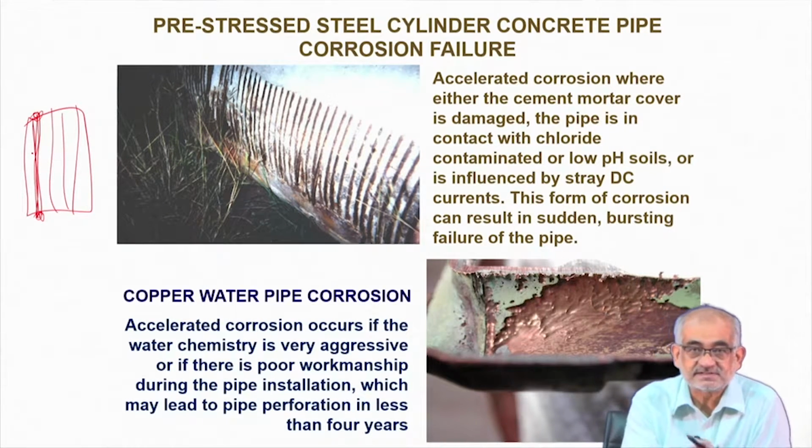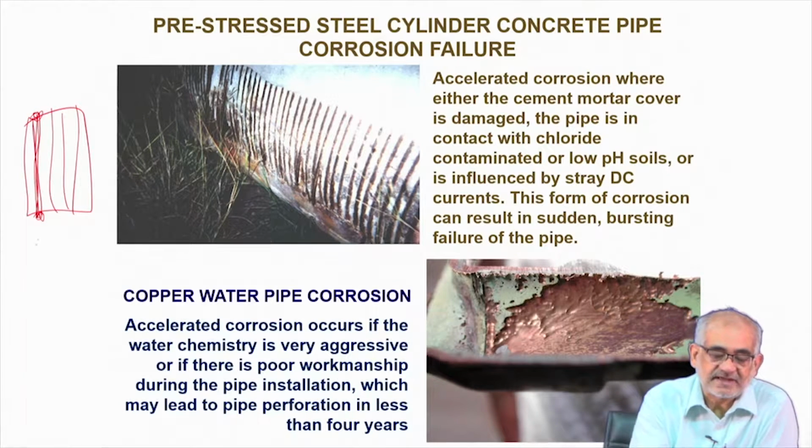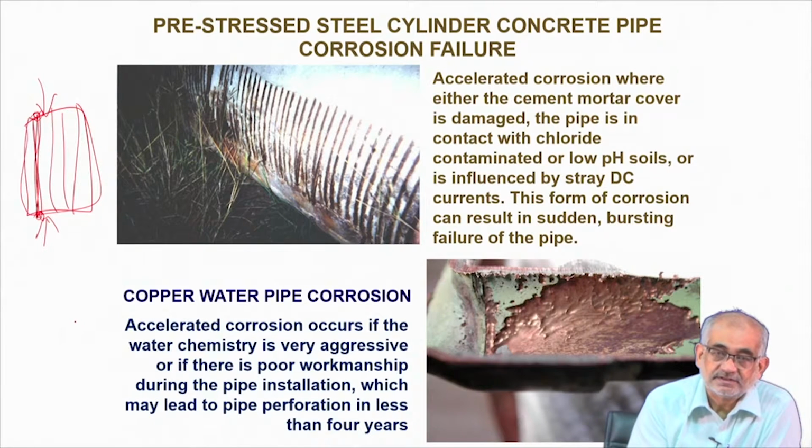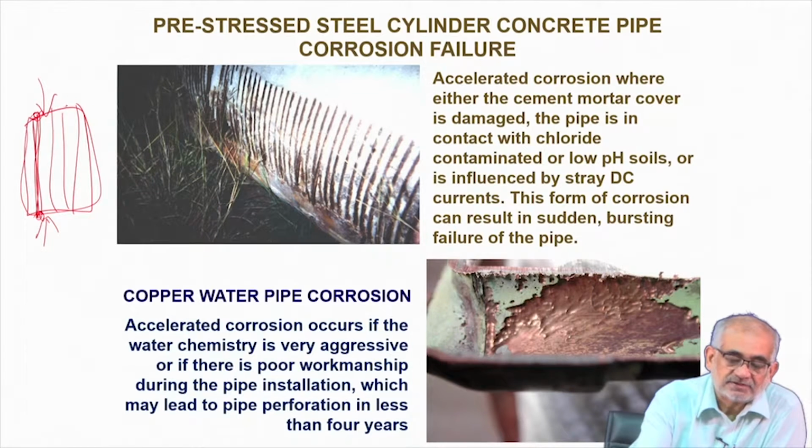And when you cast, then this stress will actually create a residual state of stress on the surface of the concrete, which will be compressive in nature, acting towards each other. So the material, when you actually release, will tend to relax, will tend to actually expand, because you applied some mechanical forces to compress them.